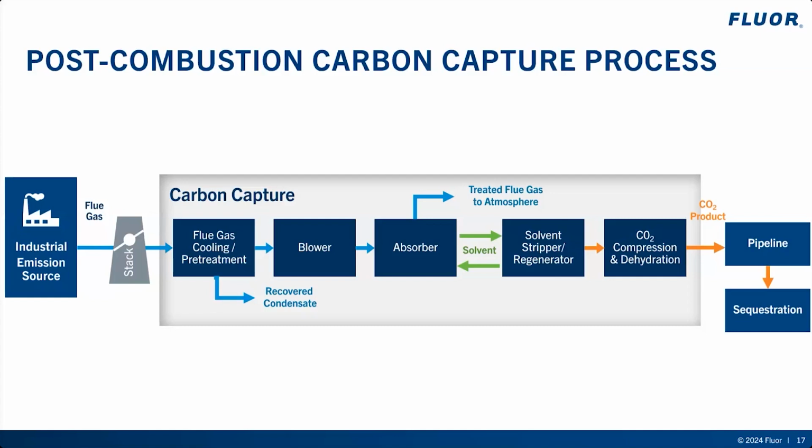The chemical absorption of CO2 by the solvent is an exothermic reaction, and additional cooling is required to remove this heat of reaction and minimize excess water losses from the absorber vent.